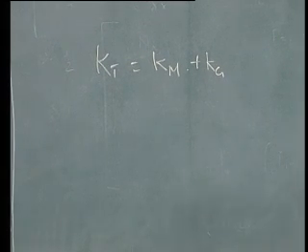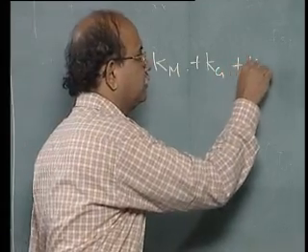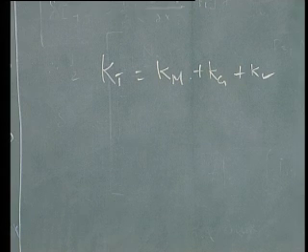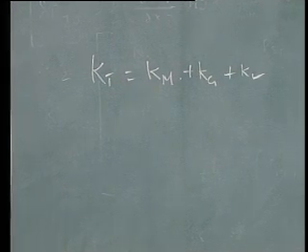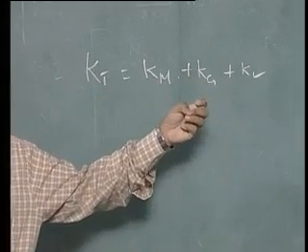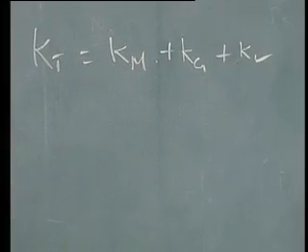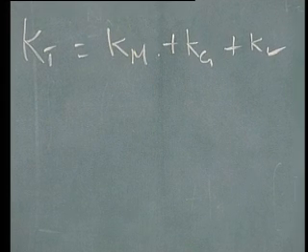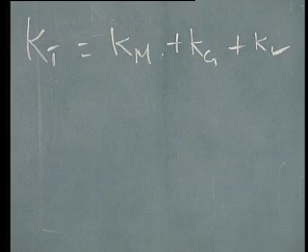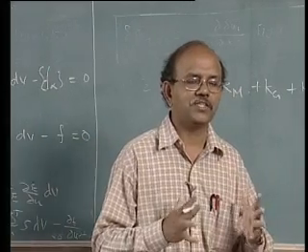And the last term is due to the load, and that is called the load contribution to stiffness. Because we have split this into BL plus BNL, or in other words there are nonlinear terms associated with B, the stiffness matrix has contribution from geometrical changes as well. Now these are what are called the stiffness terms due to load. Sometimes people call these follower forces.